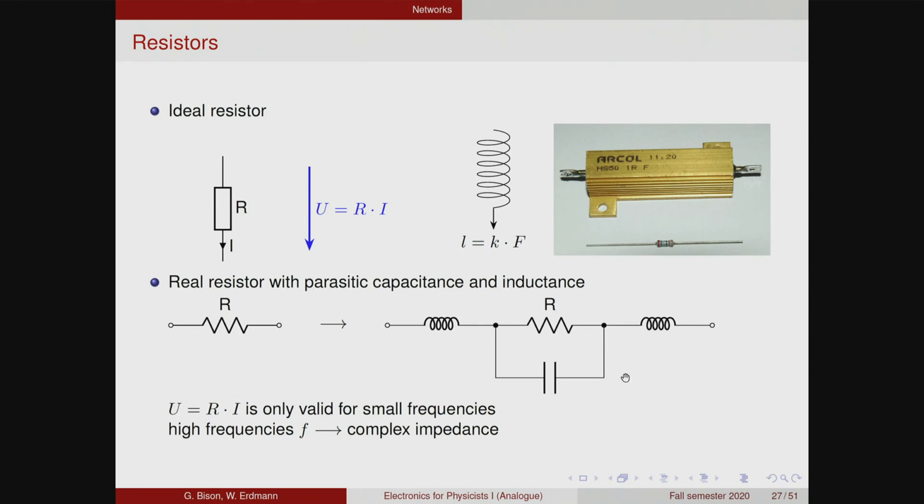Now, given that these other components have frequency-dependent resistances, so to say, this means that Ohm's law is only valid at small frequencies. And if you want to use a resistor at a high frequency, you have to be aware that the resistance might change, and you have to compute with complex resistances or impedances. And this is an important subject that we will cover in a later lecture.